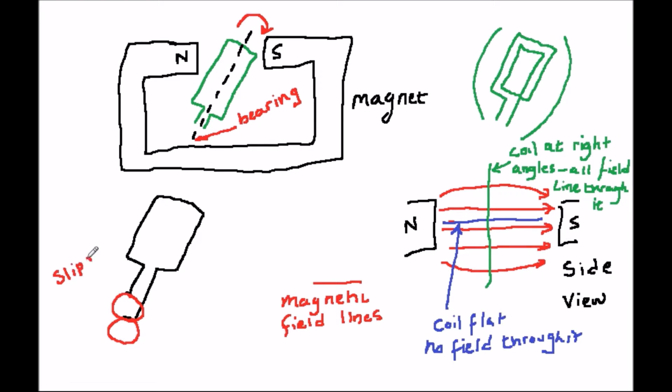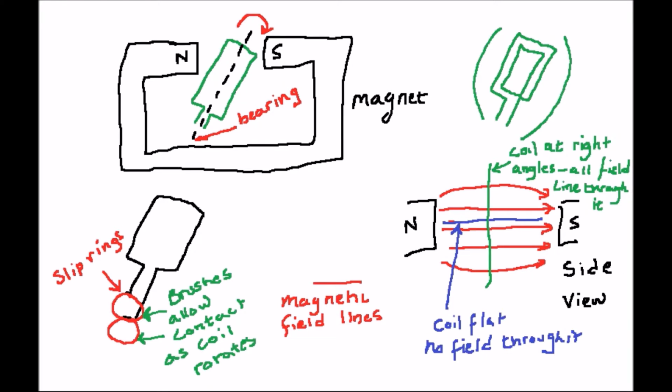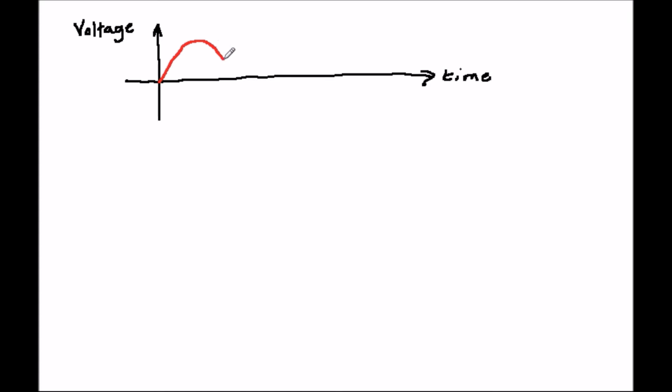The voltage or current generated like this can be plotted on a graph with the voltage or current on the y-axis and the time on the x-axis. If the rotor starts at a position when no voltage is generated, it will rise as shown in the graph when the rotor turns, and when it reaches 180 degrees, the voltage will go negative.